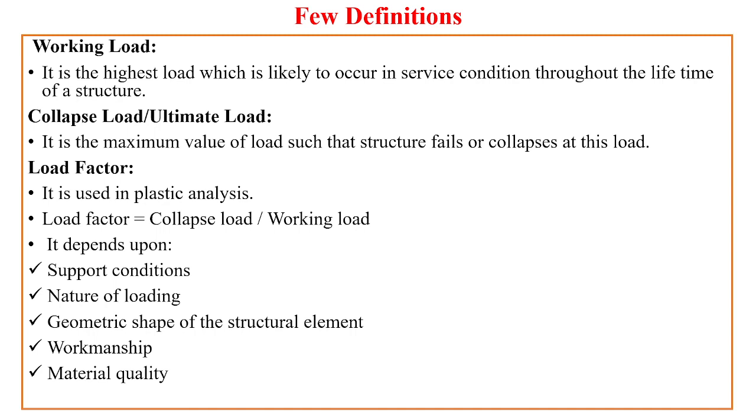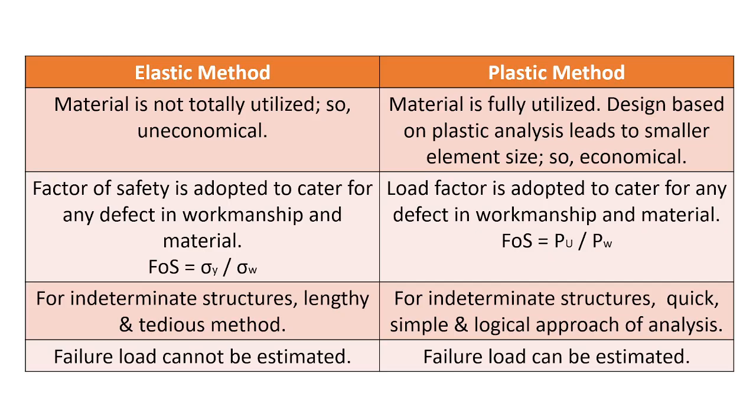Now let us see what is load factor. This load factor is used in plastic analysis. It is defined as ratio of collapse load to working load. This load factor depends upon various factors such as support conditions, nature of loading, geometric shape of the structural element, workmanship, and quality of material.